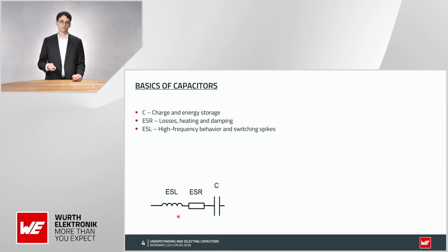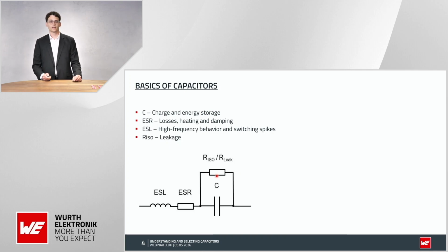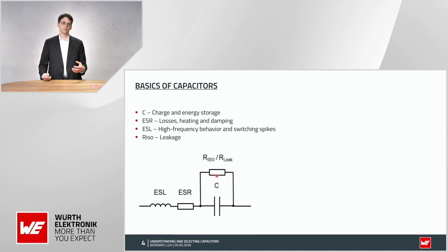Then, for sure, we also always have some inductance, which is especially important in the high-frequency behavior of this capacitor. And then, for capacitors, we always have the insulation resistance or leakage resistance, which means the smaller the insulation resistance is, the higher the leakage current is. So therefore, the insulation resistance should be as big as possible, for sure.